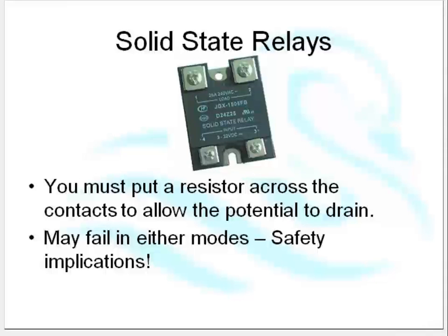Okay. The next thing is, if we're outputting from our digital output to a heater, we're typically going through a contactor. Now, I'm not going to use a contactor, because if I switch a contactor twice a second, it's going to be stuffed within a week. So what I'm going to do instead is use a solid-state relay. A solid-state relay, to all intents and purposes, is a silicon contactor. It's a contactor with no moving parts. It's really a great big transistor.